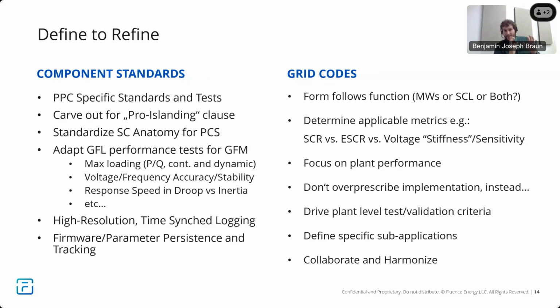That's a small enough system where this battery, especially when other thermal generation is off, has to provide a certain amount of fault current to reliably trip protection, and not just a nice bolted three-phase fault, but also harder to detect single-phase faults.